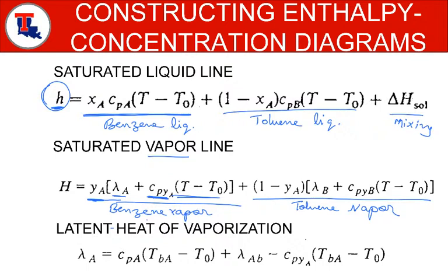Okay, now then comes how do you calculate the latent heat of vaporization. The latent heat of vaporization, again, that's a tricky part, because that's a function of temperature. So latent heat of vaporization again is a tricky one to calculate. So you have to take Cpl and Cpv. So these are the m Cp delta T, the sensible heats in the liquid phase, sensible heat in the vapor phase, and you're adding that. See how complex the calculations become?